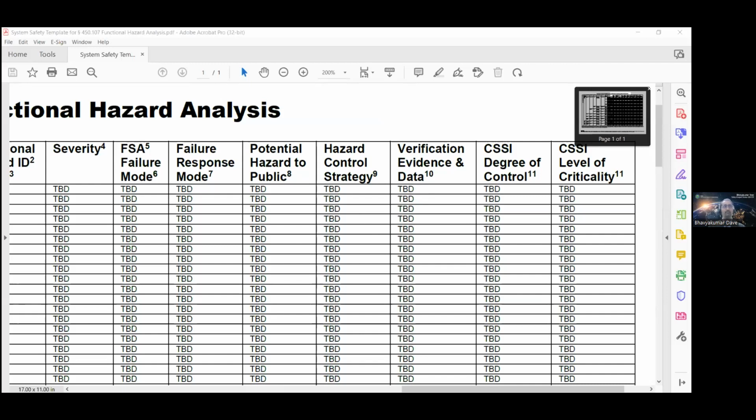So let's take, for example, the system safety functional failure of a thrust vector control actuator failing due to any particular cause. For a TVC actuator failure, the applicant may map that failure to, for example, an off-nominal trajectory failure that results in a malfunction turn vehicle response. So that is the type of data that should be populated in these two columns by the applicant for each functional failure during each phase of flight that could present a hazard to the public.